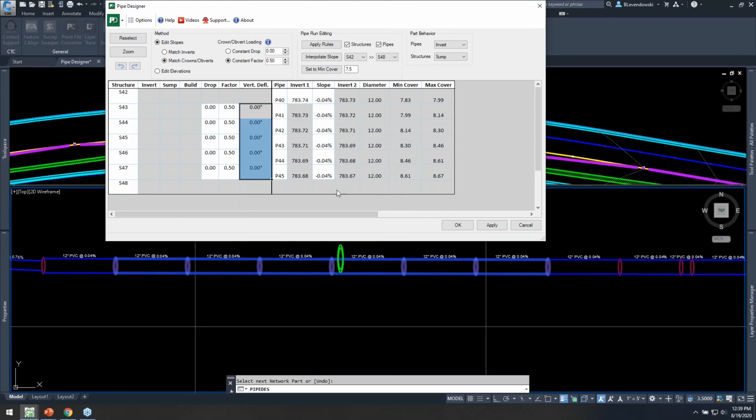So I've got vertical deflection. I'm not gonna put bends in here. I'm gonna attempt to just slope this water main down and then back up to avoid that storm line. But my deflection is, of course, a concern in dealing with that. So let's grab these 2 pipes, this one here, and this one here. We'll slope them down, and then these 2 will slope back up by a similar amount.